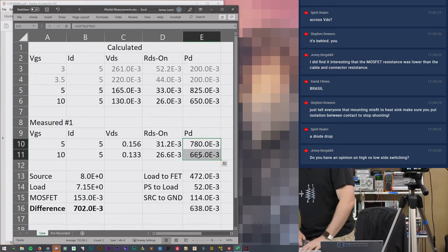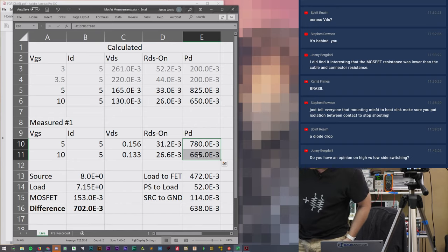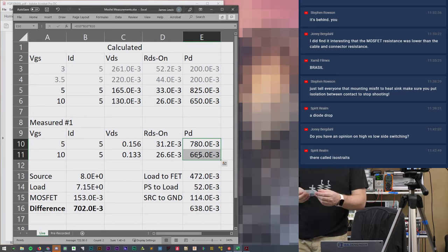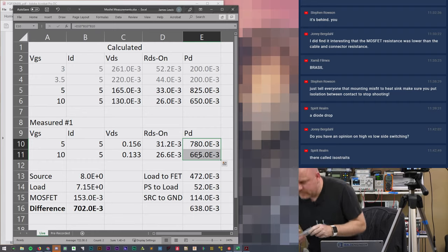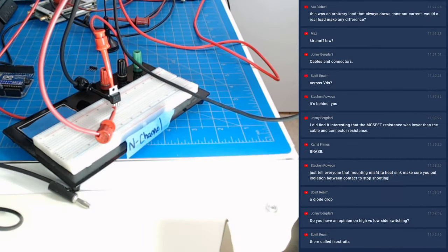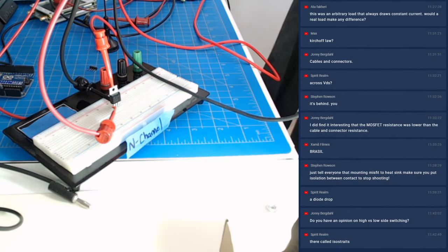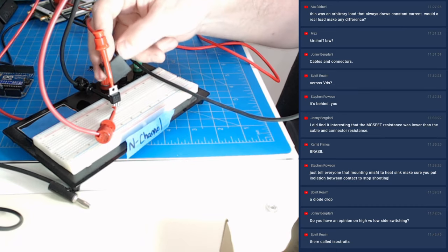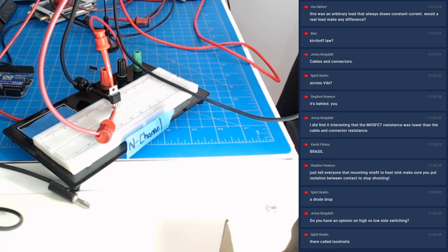Okay. I actually have some heat sinks that are designed for TO220s, but instead I'm just going to make a point with these. All right, let's go to webcam. So, for example, if I have a heatsink, I would not want to just attach that directly to the back of the transistor.